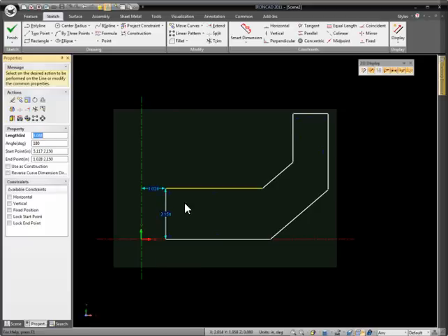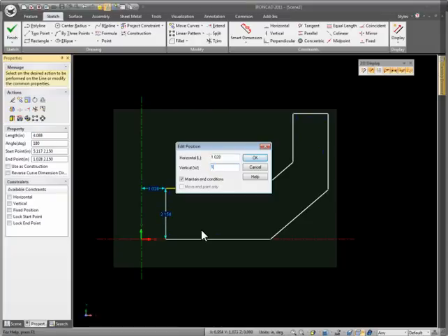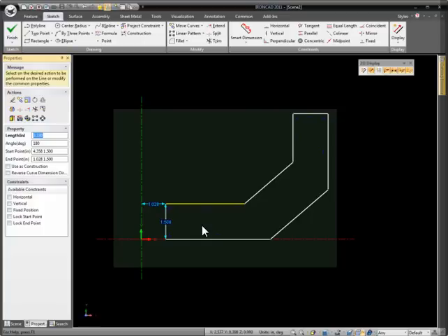If we want to set the height on the other curve, we can do the same thing, just selecting the other line. It's giving the information for us to drive it vertically. Maybe we want to set that to 1.5, we can drive that element. Notice that I'm not selecting the vertical line to drive its height, because this is not a curve dimension, this is a position, so it's positioning the endpoints. So you want to actually pick the curve that you want to move horizontally or vertically. For example, if you pick this curve element, this will drive it left or right. If I wanted to move it up and down, this curve will be used to move it up and down.